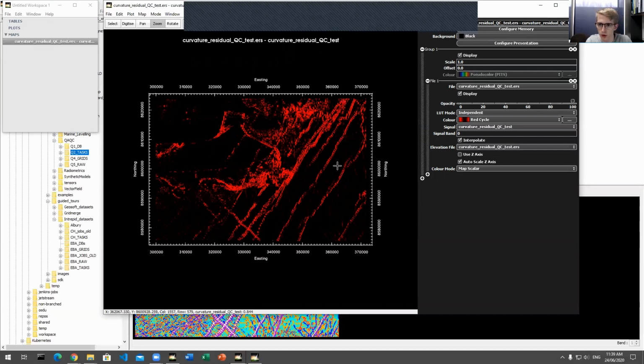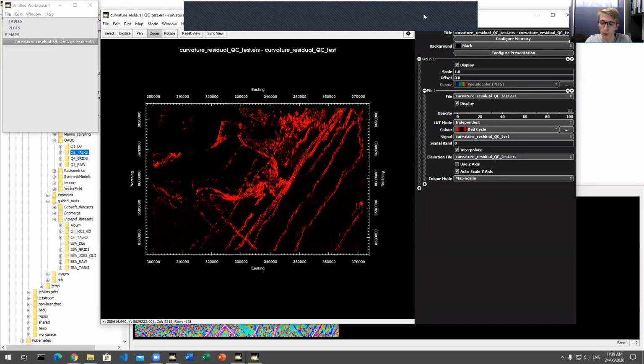Another more in-depth process would be to verify if you have honored your data once you have gridded it. So a way we can do that is using the data refactor tool. So after we've produced a grid, we can put it into this tool and push the values at each data point back to the original data points. So this is a way to check to see how much a gridding process has modified your value, so that you can have a bit more confidence in what the gridding process does.